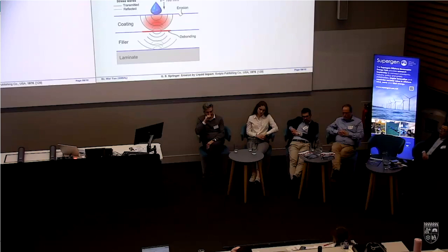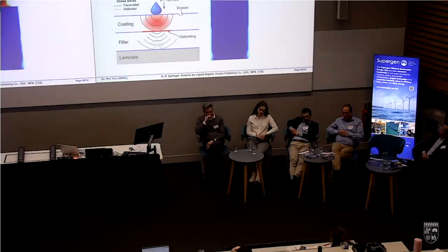And you can see droplets bouncing at the interface. After millions of these drop impacts, you have this debonding and erosion happening. And we have established a computational framework basically showing the stress wave traveling, essentially starting with the contact point and gradually going through the solid until you reach equilibrium.